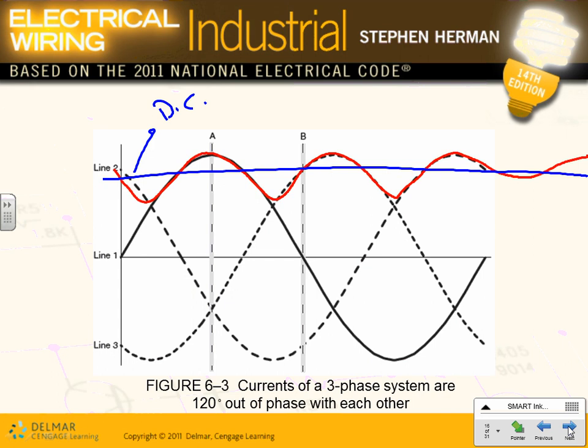Look at that. When you add all these signals, ignore everything else. Just go from here right on this. So as phase A goes down, phase B takes up. See how they keep the voltage right at the reference to the equipment. So long story short, that's where AC three-phase is superior to AC single phase, because it's closer in terms of DC. You can see it doesn't go to the zero. Can you see it doesn't go to the zero here? When one is going to the zero, the other picks up.